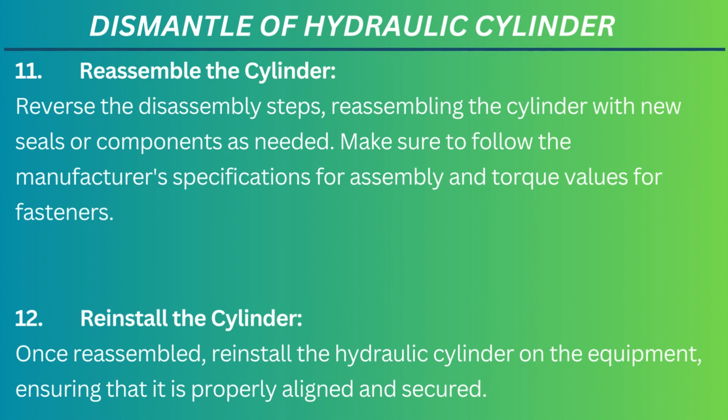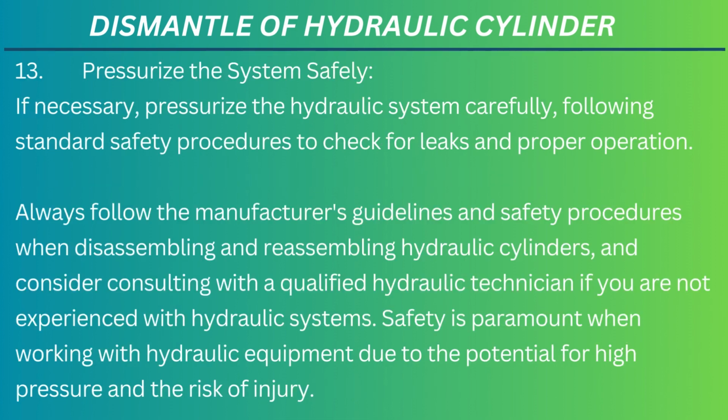12. Reinstall the cylinder. Once reassembled, reinstall the hydraulic cylinder on the equipment, ensuring that it is properly aligned and secured. 13. Pressurize the system safely. If necessary, pressurize the hydraulic system carefully, following standard safety procedures to check for leaks and proper operation.